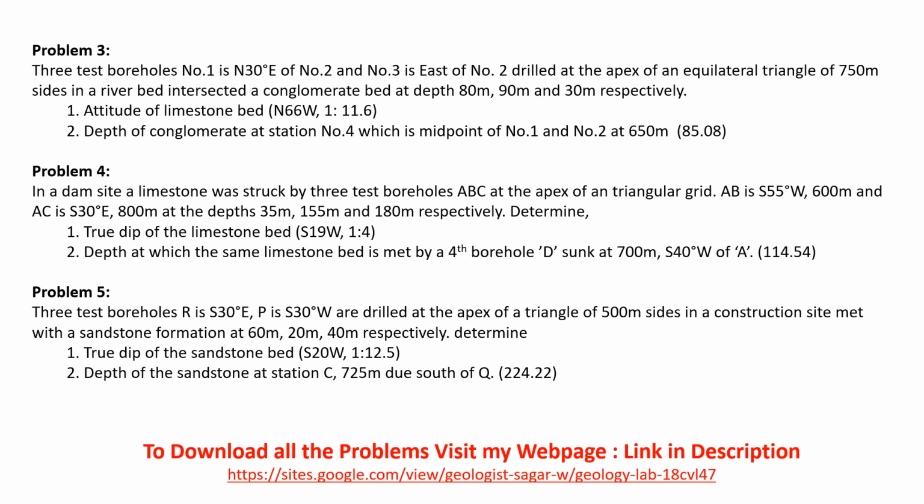So once you plot it, you should measure the distance between borehole number 1 and borehole number 2 after plotting the dip and strike problem. Divide at the center, drop that line with the least borehole and get that distance at the depth of the fourth borehole. The answers are also mentioned for your information.